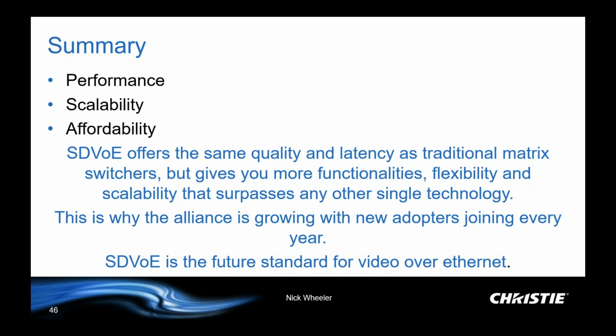Let me get another question here. Do projectors share the IP with the RX, or can they be accessed on the network via TCP, UDP independently of the SDVoE system? Yeah, that's a really good question. I didn't get into too much detail on that, but the IPs can be a completely different IP range from the TX and the RX. Okay, so the projectors in Zurich Opera are in a completely different range than the TX and the RX.